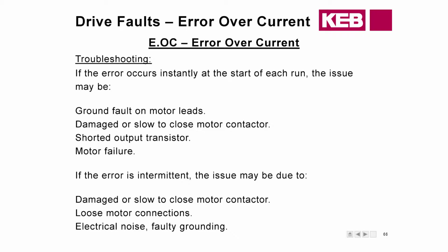If you are still getting the error after the motor leads have been disconnected, that means that the short is going to be in the drive itself. So that's a really quick test to see, okay, hey, do I need to look at my motor? Do I need to look at my drive?